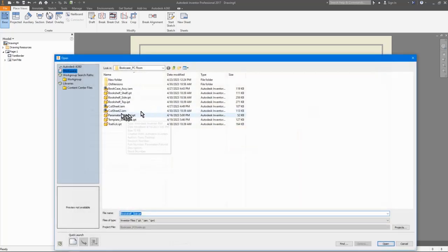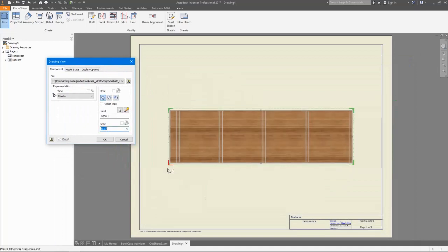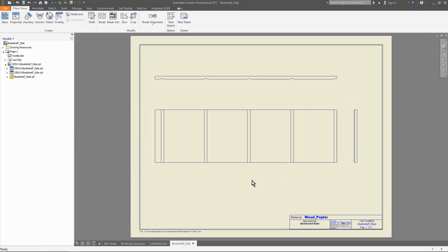Now is when I decide what dimensions are needed. The 2 obvious ones are length and width. The others are the location and size of the dados and rabbet. If this project was using materials of different thicknesses, then I would also include the thickness of each part. I left it off since they're all going to be the same.